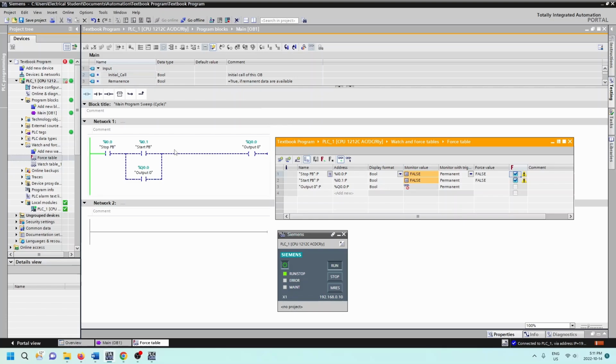All right, guys. So we've been able to look at, oh, and that's cool. Do you see that? After we remove the forces, the exclamation mark here telling us that we had forces enabled on our PLC program was eliminated, and now we got green lights all throughout here. Sweet. So now yet another tool that we can make use of, using the forcing of the bits, right?